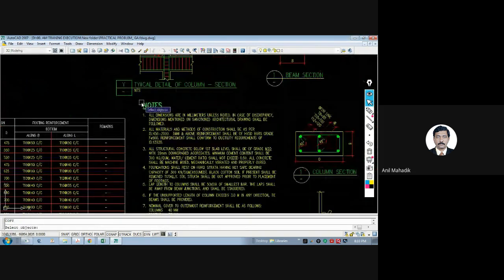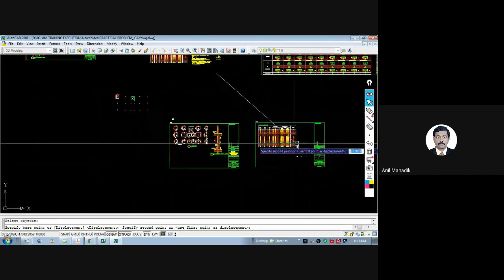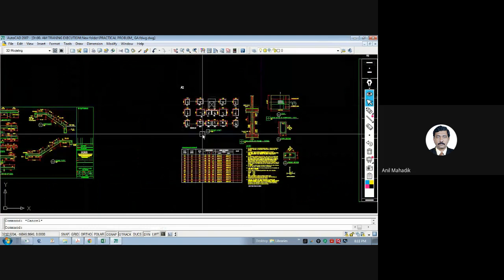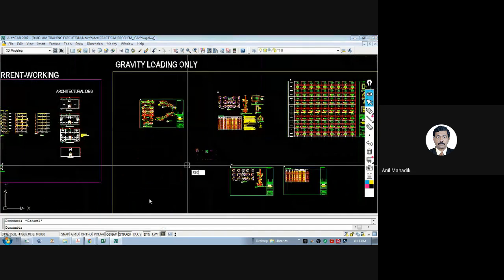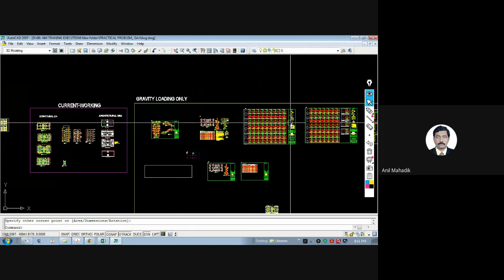See, now this drawing is a very small project. There are a lot of big projects also that we have in reality. So for bigger projects, you need to give A1 size papers. And if they are not fitting, then you can even split the drawings into different sheets. So many times, let's say this is your layout. Let's say my building is such that the width of the layout is like this. So long a building that even you cannot fit it in A1 size.